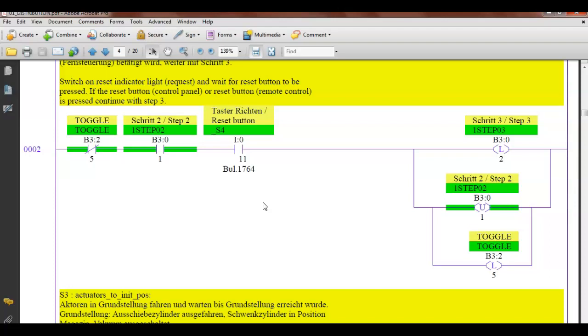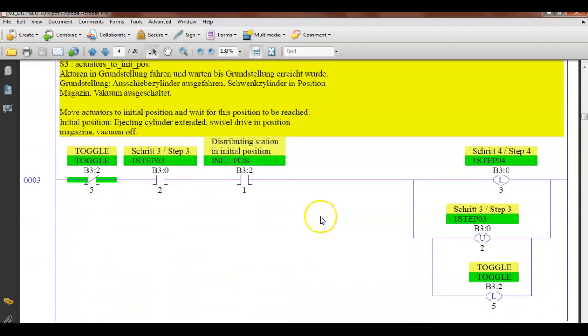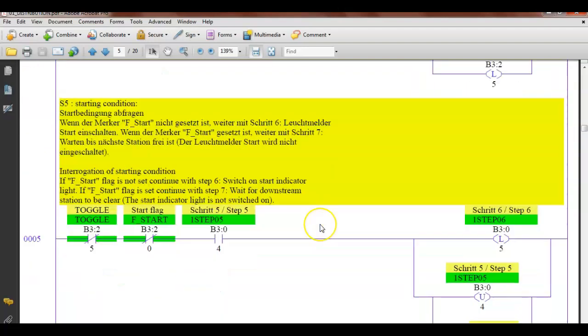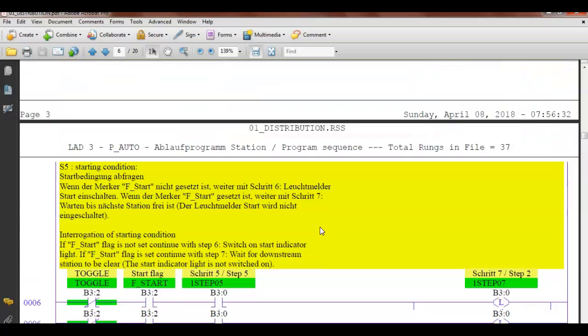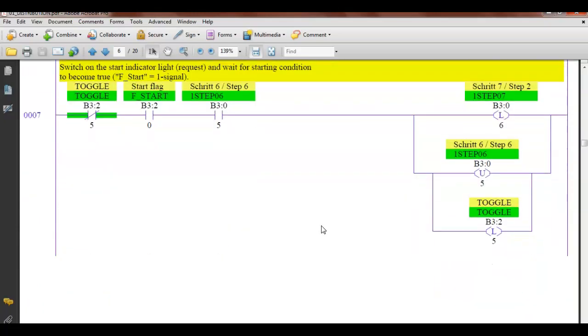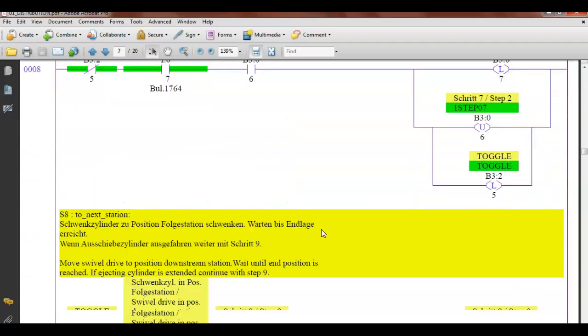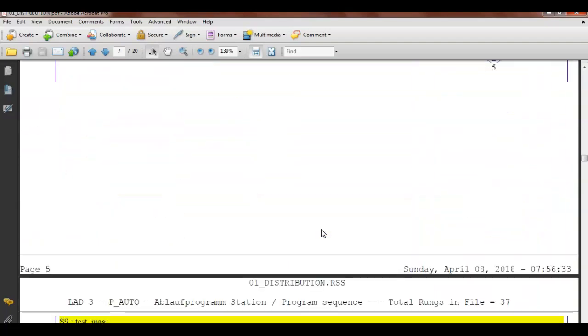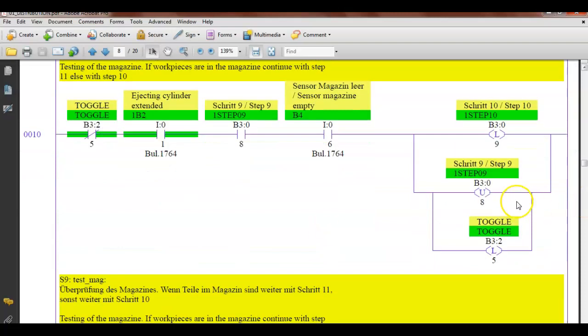So look, all these are what type of files? These are all B3, B3, B3. Look at, if they had to use an output for every one of these, so there's 6, right? There's 6 already. There's 8, so now I'm screwed, because I don't have this many outputs. But this guy here does not control anything. It doesn't turn on a motor. It doesn't turn on a light. All its contacts are within the program.